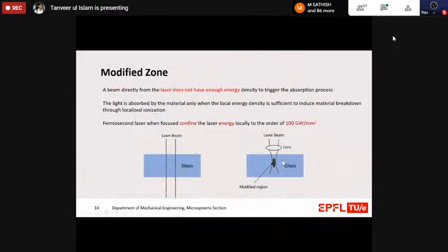you can see here, I have shown that the spot size is in an elliptical shape. And when I say the minimum spot size is equivalent to the wavelength of the laser light we use, that means the thickness of the spot will be around that dimension. However, the length of the spot is much more than that. For example, in one of the laser systems that I worked on, the spot length was around 10 microns and the diameter around 1 micron. In another system, it is around 20 microns with a diameter of 3 microns.